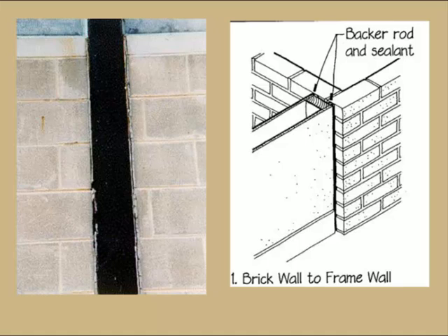Well, Mr. OSHA there definitely does not meet the OSHA criteria. He's not wearing a hard hat, for the most obvious one. But you can't tell very well from that picture, he is up on a scaffolding system, and there's no tie-off for him or any of that type of stuff. But what he is doing up there is providing caulk seal where those two different wall sections come together. One is an original masonry, and to the left there is actually a clad frame system of precast materials. And then to the right, what we're showing there is that you can see the backer rod material coming out of an isolation joint.